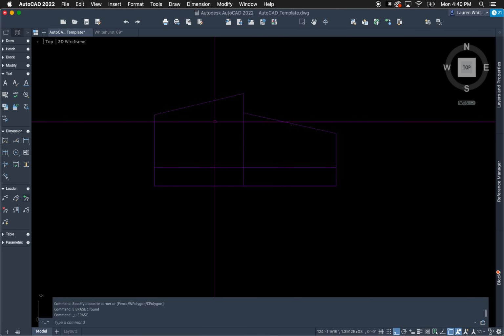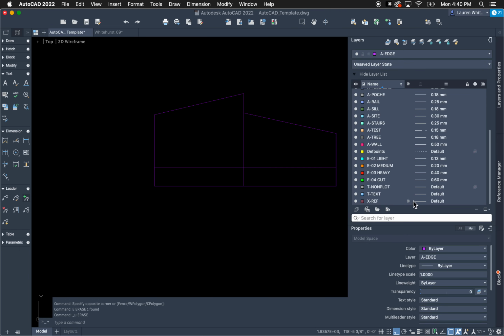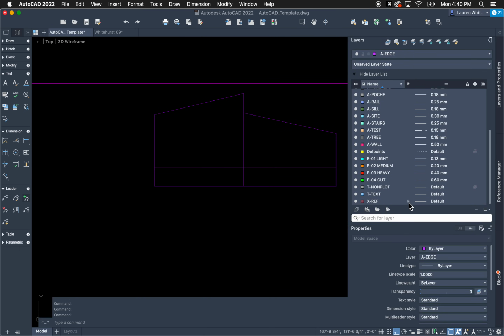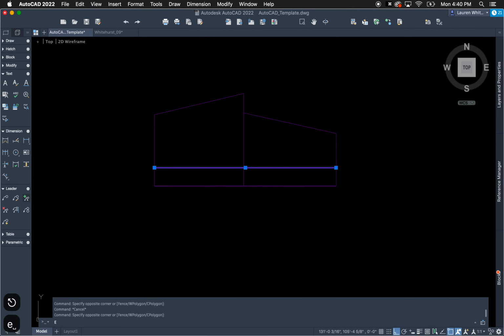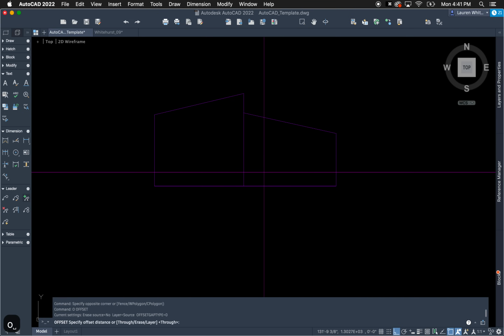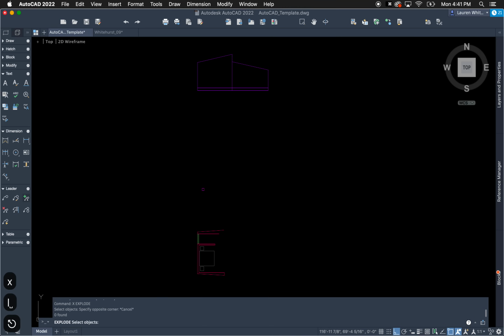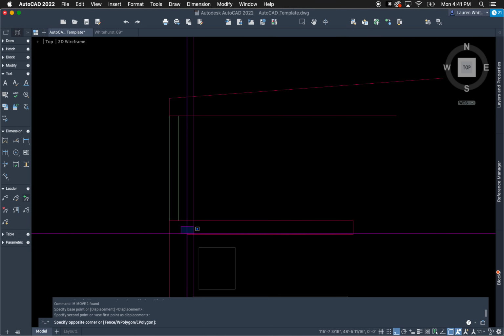But so in creating the section, I can look at pictures, but I also can use that elevation drawing that I've imported, because I know that in section, the building has to be within the boundary of the elevation drawing that I've found, right? So it can't be any bigger than that. But so I know a couple things. There's going to be some structure in there. About a foot is probably fine for now to assume. When you're designing projects in real life, you'll know those actual dimensions, but we're just guessing because we don't have an actual section.